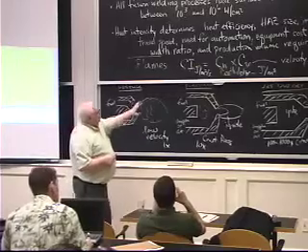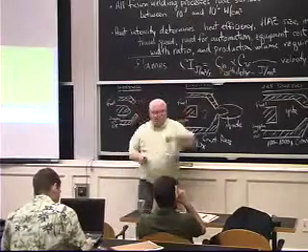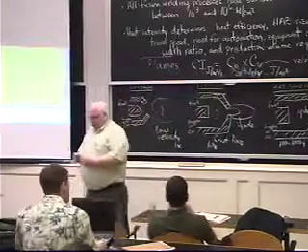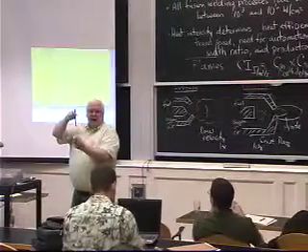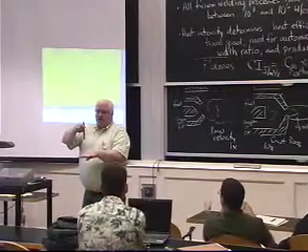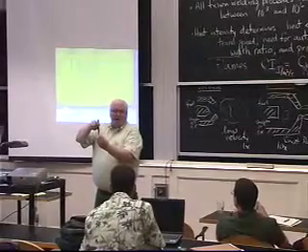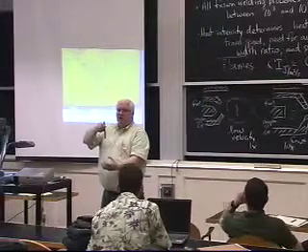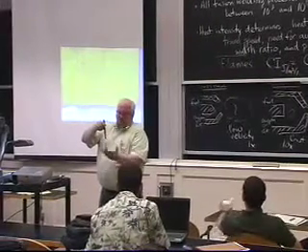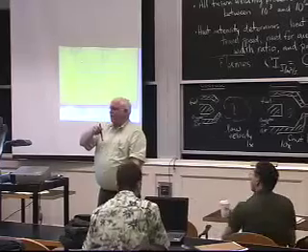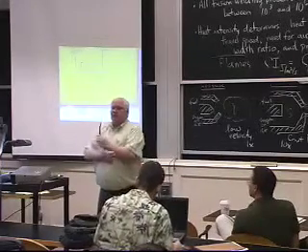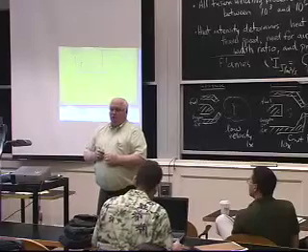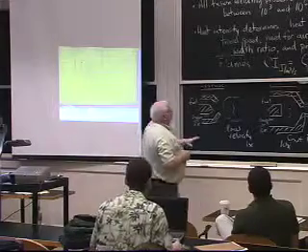If you actually calculate a theoretical combustion intensity, so I've got my torch, shooting out gas against the surface, and I figure out how much energy is hitting that surface versus how much is being transferred into the surface as heat, I find it's only about 1 or 2% efficient.